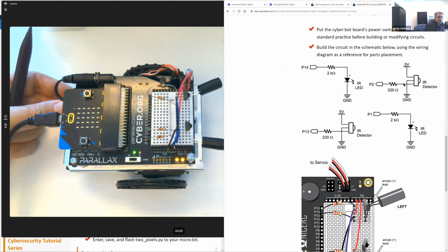So we use resistors in place of jumper wires to connect to circuits that are connected to IO pins, basically to make sure that certain mistakes won't damage the microcontroller that's underneath the breadboard here.